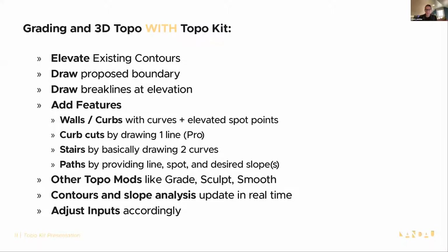From there, you have a mesh. It gives you a mesh, and then it's cutting contours. You can cut contours live while you're working and manipulating these features, and you can actually turn on topo analysis as well to see what the slope is.